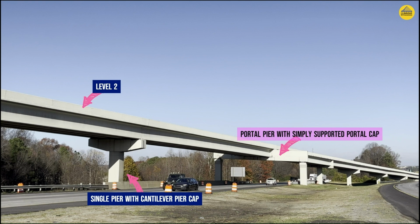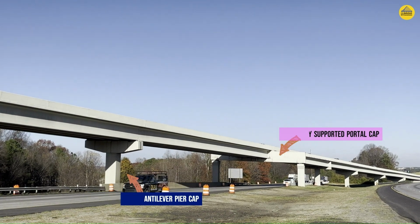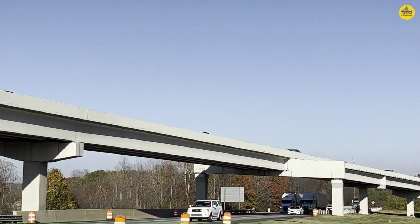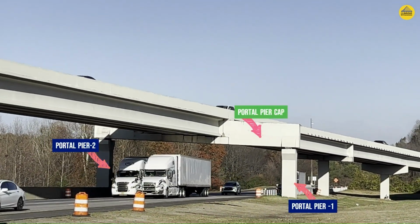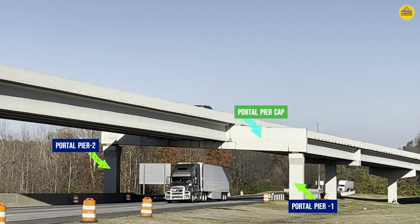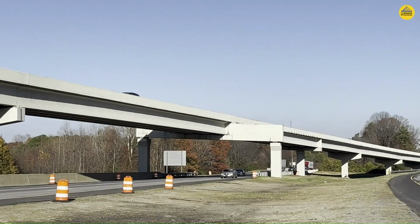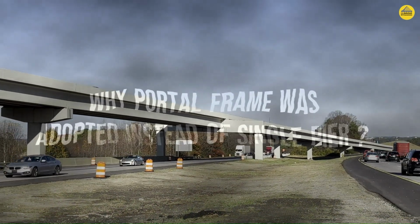This girder plus deck type superstructure is supported on multiple vertical supports. Most of these vertical supports comprise a single pier with a cantilever pier cap, but one of these supports also has a portal frame, in which there are two portal piers at the ends, and these are connected via a horizontal portal pier cap, which in this case is not rigidly connected to the vertical portal piers but is simply supported. We will see a zoomed section of the same, and before that let's understand why a portal frame was